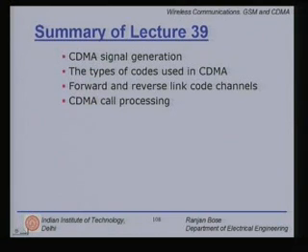Finally, to put things in perspective, we talked about error control codes and compared the error control codes used for GSM and CDMA technologies. We have seen that block codes, cyclic redundancy check codes and convolutional codes all are used in the various wireless standards. Because the wireless channel is a fairly hostile channel, it is a bad channel and it has to be protected. We also saw that we need to protect the traffic channels as well as the control channels.